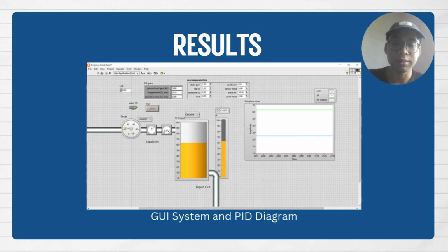As you can see here on the left in the inflow pipe, we have the flow transmitter, which measures the flow rate of liquid that enters the tank, and the LCV, which is the level control valve, which controls the liquid that enters the tank and receives the signal from the PID output to open or close so that it can reach the set point.